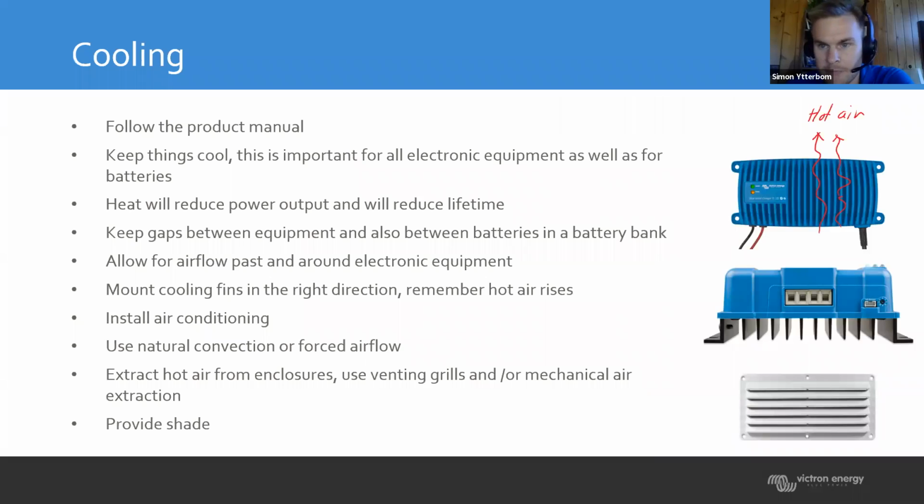Cooling, something else we talked about with the extraction fans. Try to keep your units at room temperature if at all possible, because every producer, every charger, consumer, inverter, and so on will produce heat when they're working. So try to move that air around to keep them as cool as possible. It will only prolong the life of them, and help keep the power output of them as high as possible.